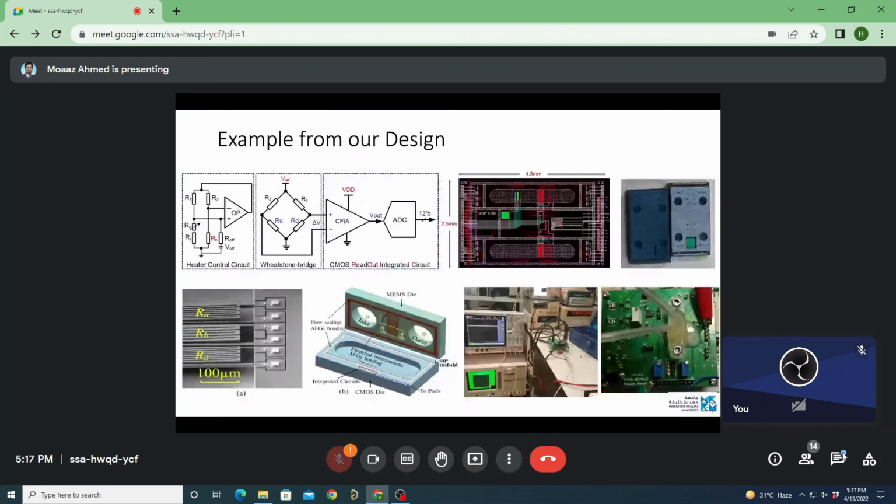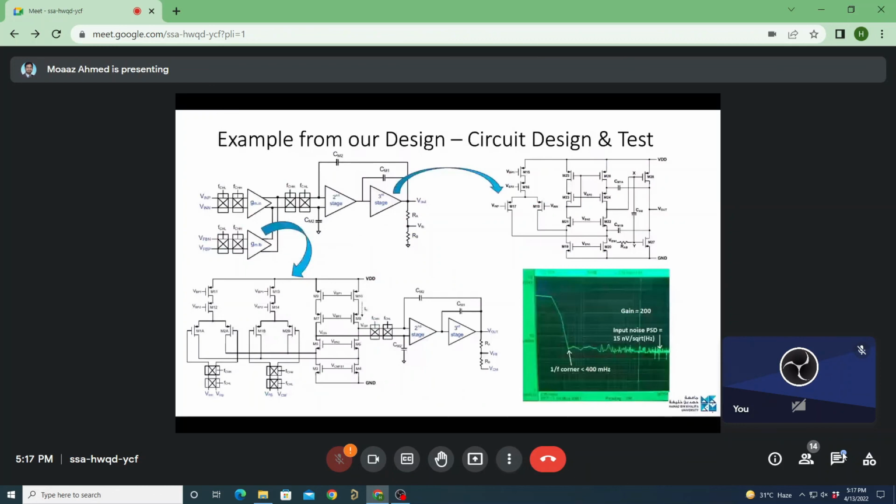So we have a folded cascode topology where we have M1A and M2A. These are the input pair. We have M1B and M2B. This is the feedback pair. Both of these transistors at their input are connected to 2 choppers: 1 chopper at the high frequency, 1 chopper at the lower frequency. Why am I using 2 choppers? Because if I use 1 set of chopper, there are non-idealities as I talked about. We have chopping ripple and we have residue offset.